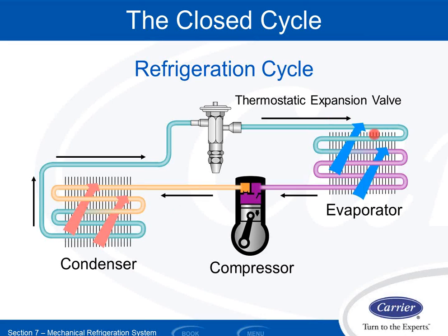So he absorbs all the refrigerant here. He moves to the compressor, rejects his heat outside, and condenses that gas, moves his way back to the TXV. The evaporator and the condenser are yin and yang to each other. They're exact opposite. One evaporates the refrigerant, one condenses the refrigerant. The compressor and the TXV, thermostatic expansion valve, those guys are the yin and yang opposites of each other.